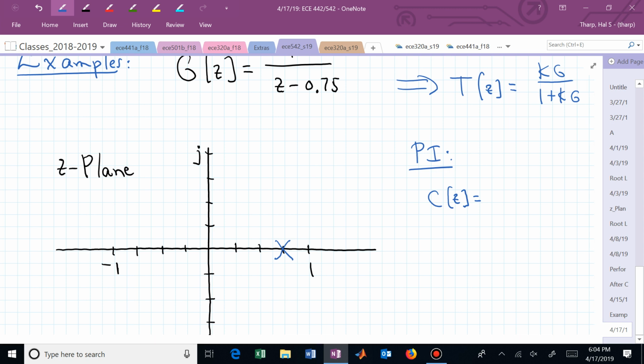Now if I put in 4, and if I can stabilize this system, I'm going to have a 4 coming out, aren't I? Because I now have located a pole at z equal to 1 in my forward transfer path. The C of z, G of z transfer function now contains a pole at z equal to 1, which is going to give me 0 error to a constant if I keep my closed loop poles inside the unit circle. A PI controller immediately gives you that pole factor of z minus 1.